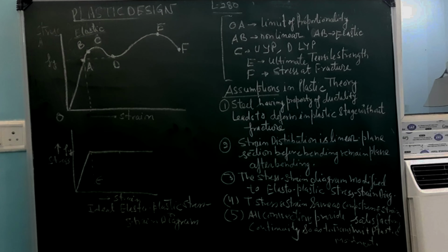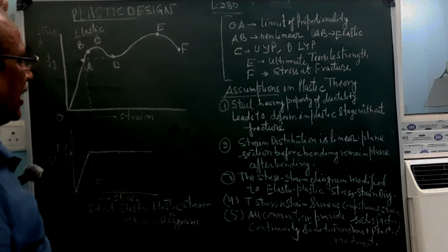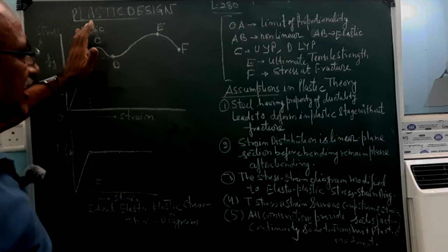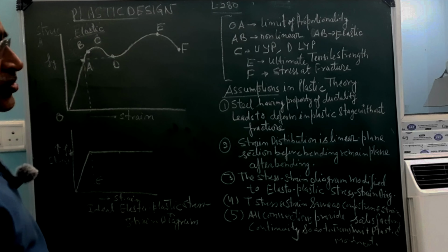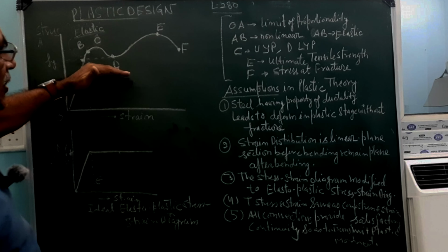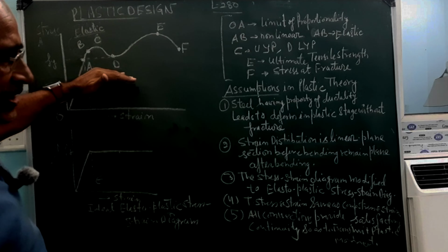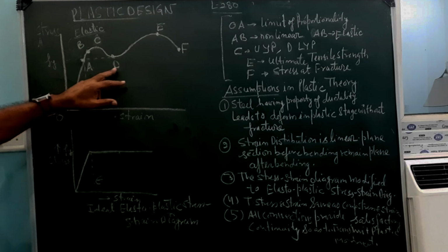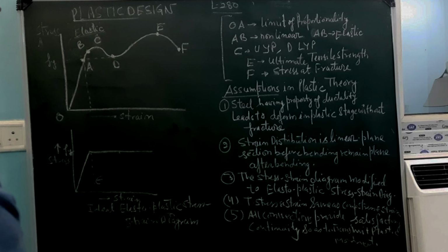and we get a point D, which is lower in respect to C. If you read in the dial, the higher reading is coming, then a lower reading will come. So corresponding to lower limit, that signals from the dial, that you note it down. That is your lower yield point.